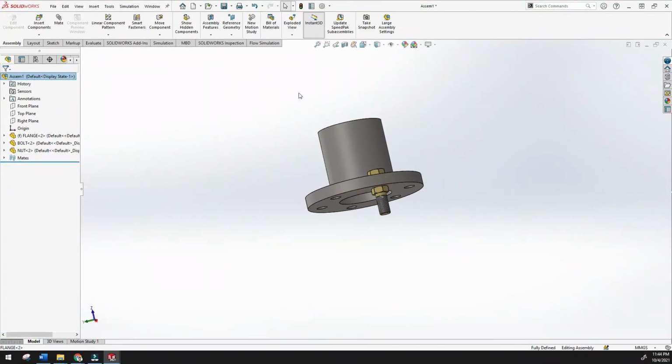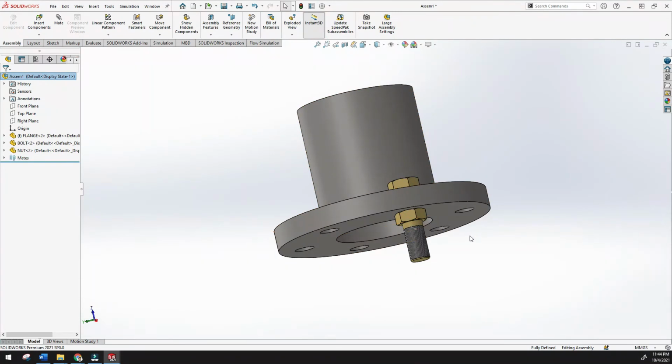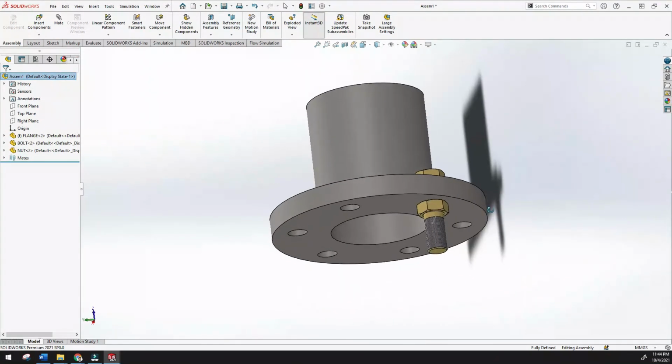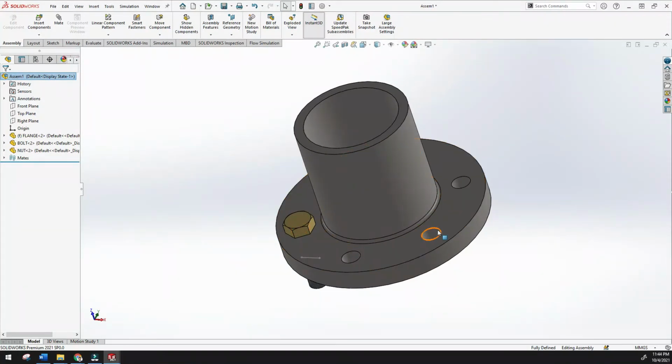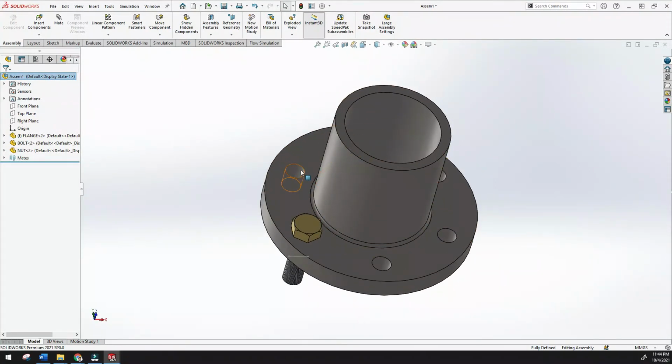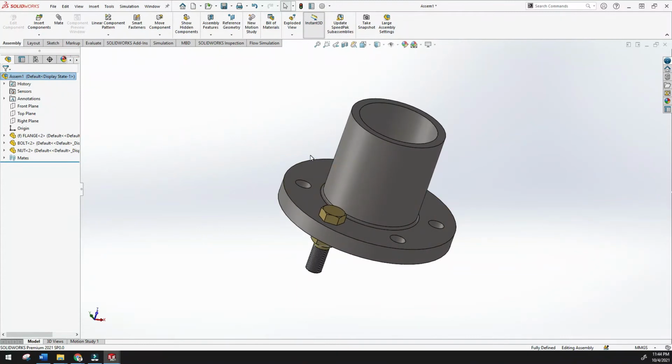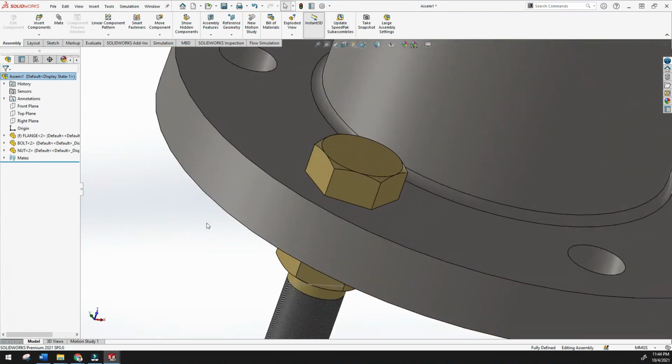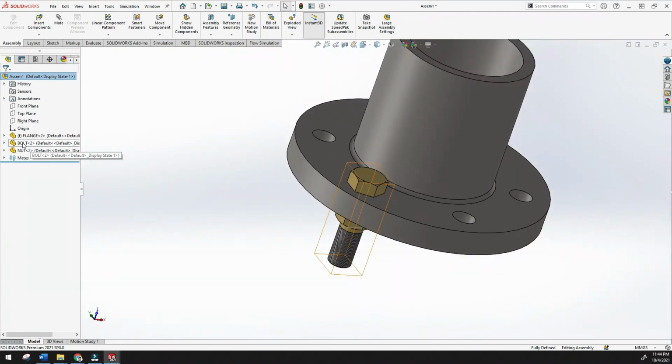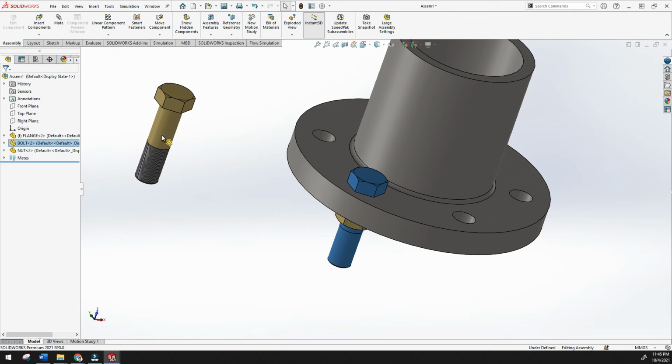See how I have already assembled this model using nut, bolt and flanges. But I want to give the remaining ones here, okay. So how to give the remaining ones here? I would have to import again, but there is no need to import because I have to give the same components. So just click here and try to move it here, it will not go this side, right? We cannot move it like this, but once you hold the left mouse button and Control, then drag to this right side, it will automatically come here.